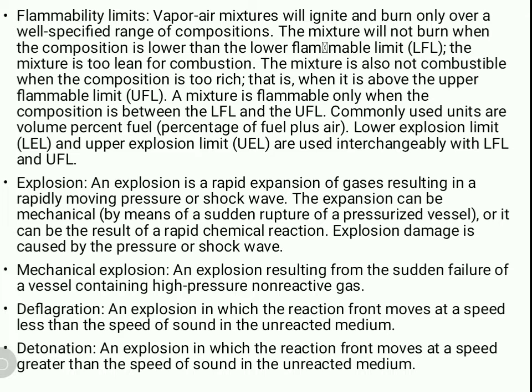Next, very important, are the flammability characteristics, the flammability limit. From the definition, a vapor and air mixture will ignite and burn only over a well specified range of composition. When the liquid is there, it will release some vapors into the air, and those vapors will mix with the air in a well specified composition and make an ignitable mixture. When given a small ignition source, it will catch fire. So this is a well specified range of composition of a vapor.